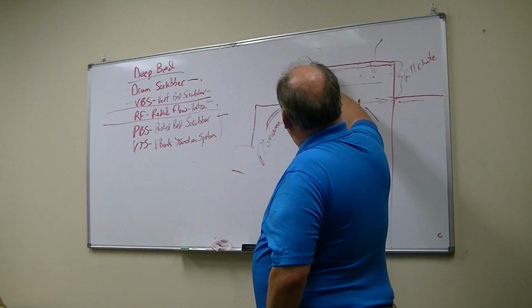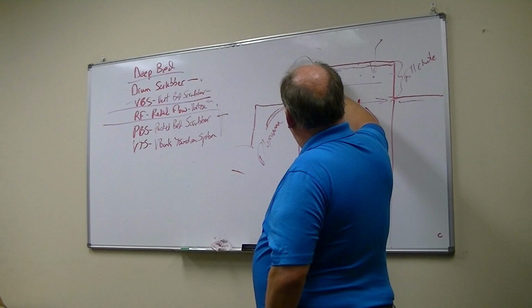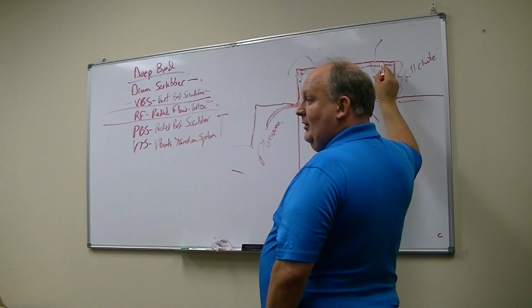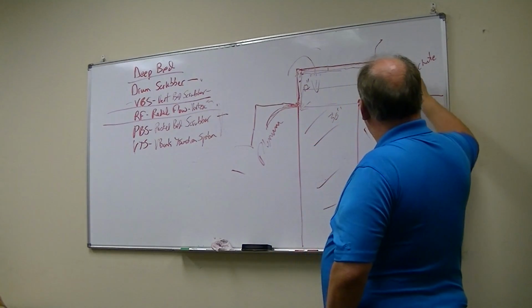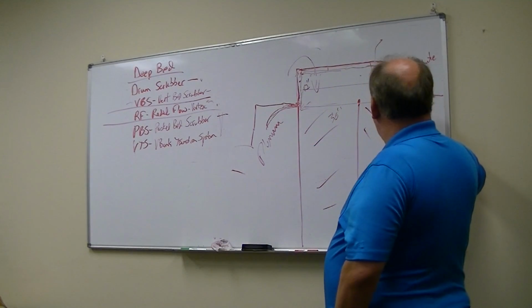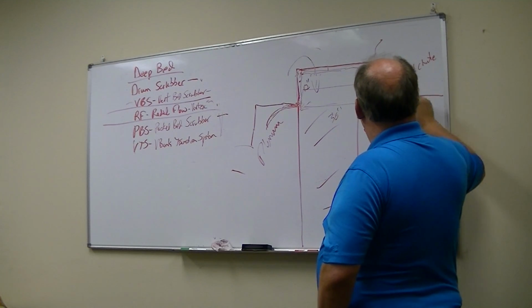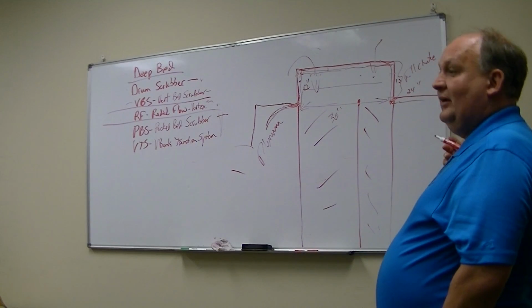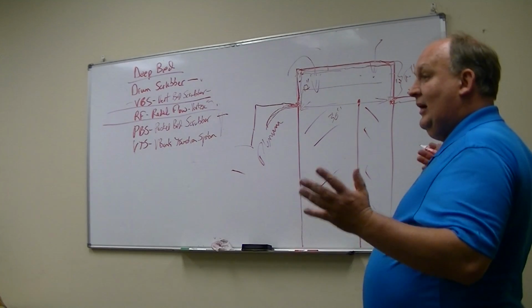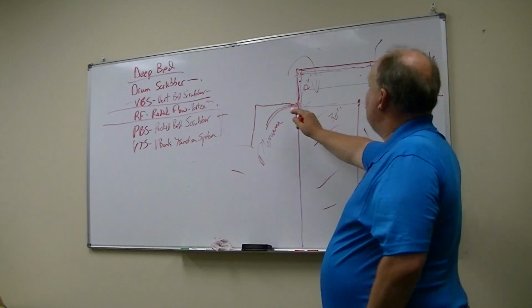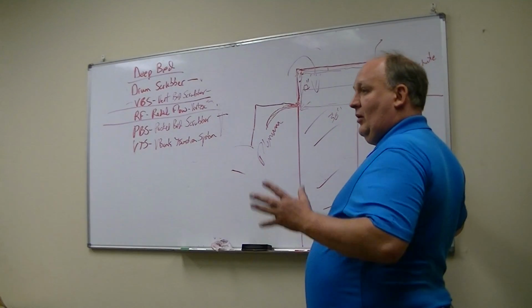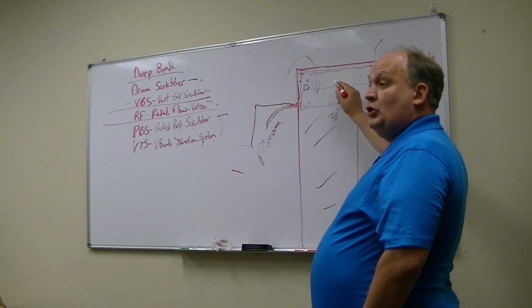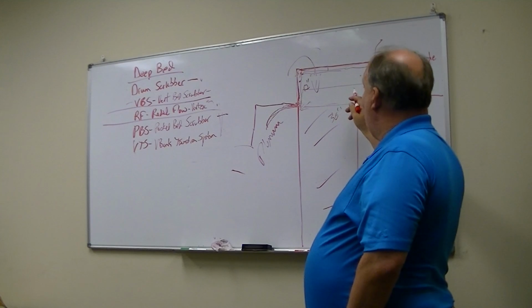It says, hey, I got an idea how to take a shortcut. Let's just go up this 12 inches. So if we have a 12-inch chute, then let's shoot down the expressway here, and then take this side street down here, and look, all I had to do is go 24 inches. And now it's super happy. It only had to go 24 inches of media instead of 36. So that's a concern for deep bed systems that we have to be really careful of.